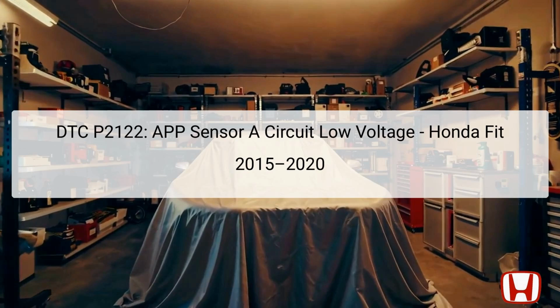The DTC P2122 indicates a low voltage condition in APP sensor A or throttle position sensor D, indicating potential issues with the throttle input to the engine control unit (ECU). This fault occurs when the signal from the accelerator pedal position (APP) sensor is deemed to fall below acceptable voltage thresholds as detected by the onboard diagnostic system.